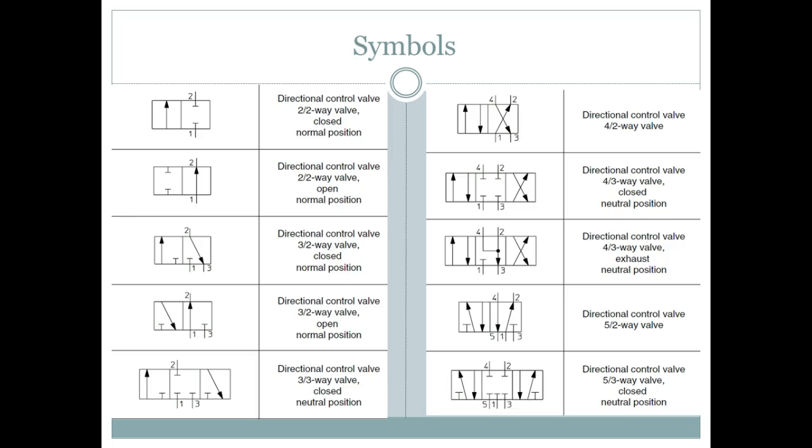So what could we do with this actuator? I could just grab it and move it any way I wanted to, right? When I move it this way, it puts pressure on one side of our piston and it goes directly to exhaust. If I move it the other way, it goes directly to exhaust too. So there's really no pressure to hold the cylinder in position. Some people call this a floating center, because it allows your actuator to float. You can move it.